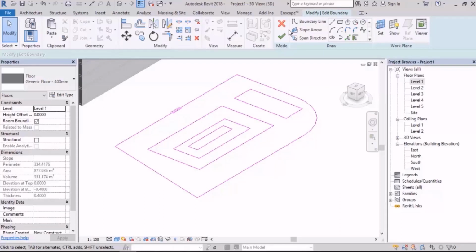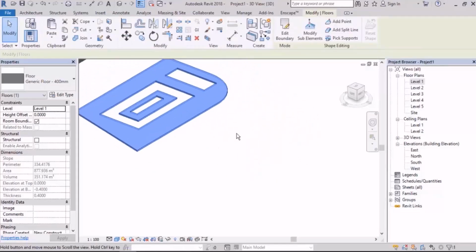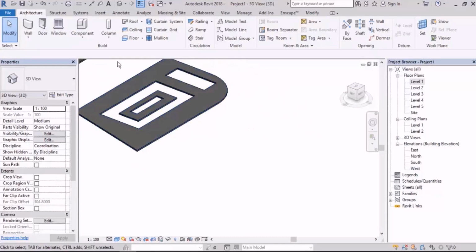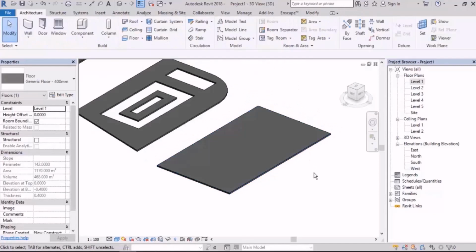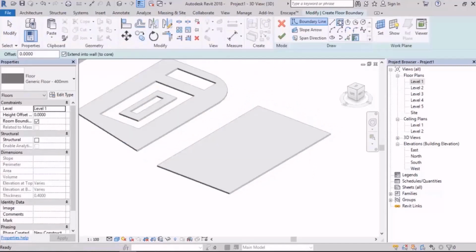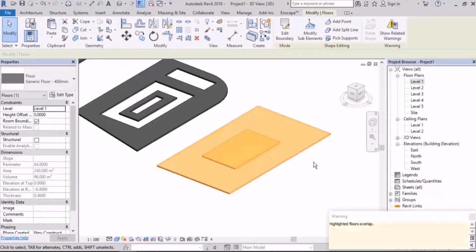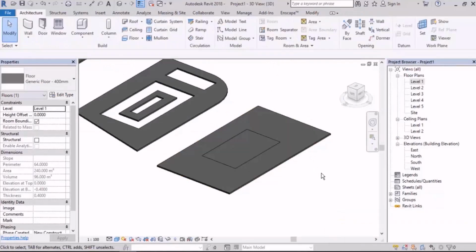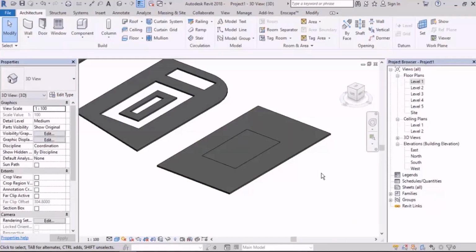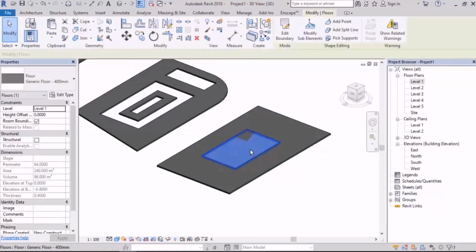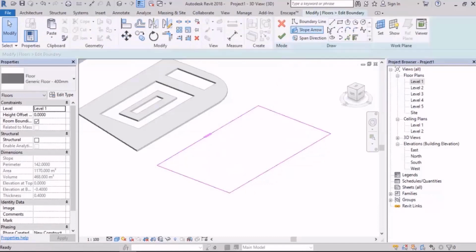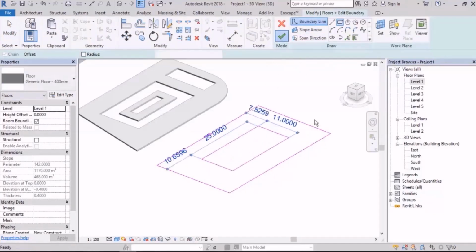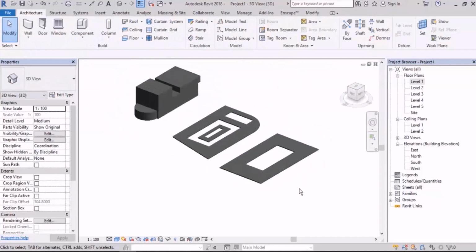And the same thing happens if I continue drawing shapes. Now I want to show you a common mistake that is made by a lot of people. Many people do this. They draw a floor and then click on finish and again click on floor and draw it on this one, and then they wonder why it's not empty. Well, it's another floor. That's not what I said. I told you that if you draw another shape while you're editing, it gets empty.